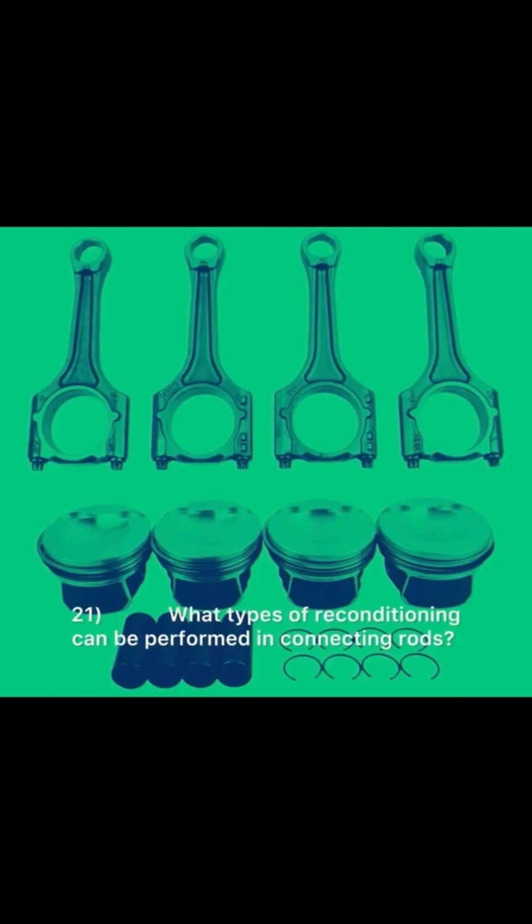21. What types of reconditioning can be performed on connecting rods? Resizing big end bore, replacing fasteners.